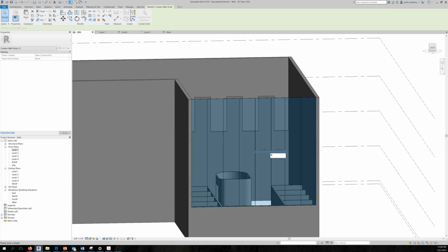So you see how it modifies the dimensions. You need to select actually the right side of it to be able to change the dimension. If I keep doing this, it will push that one to the other side, and then it will push this one to the other side. So I need to change the line I have selected. Make sure you play around with this until you get hold of it.